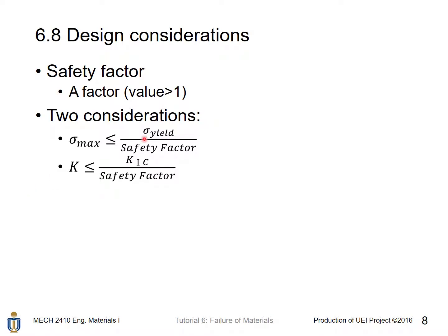The first one, the maximum stress within the object using that particular material must not exceed the yield stress for that particular material over the designated safety factor.